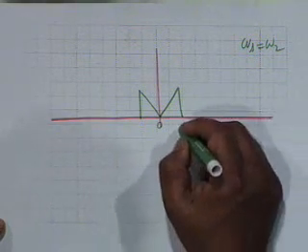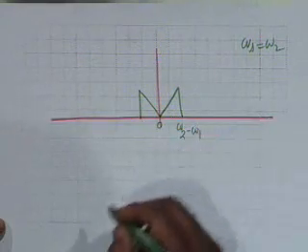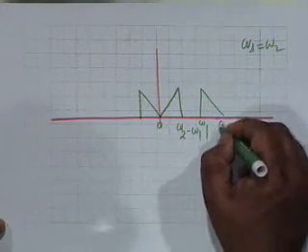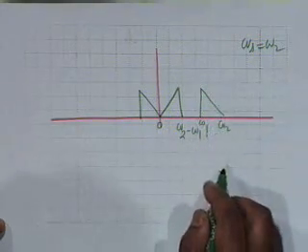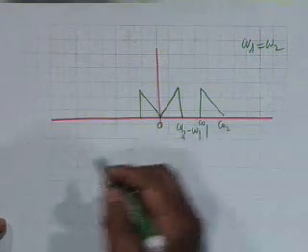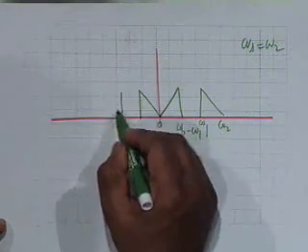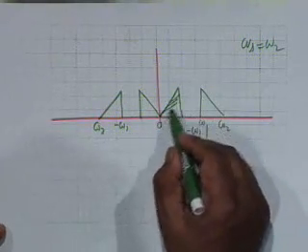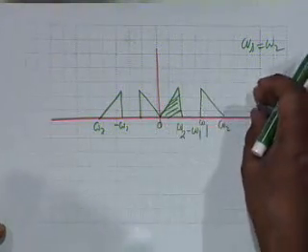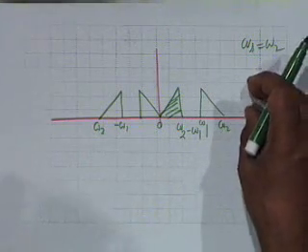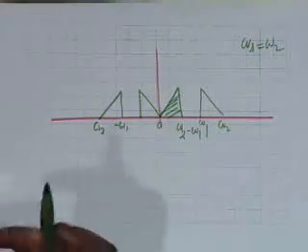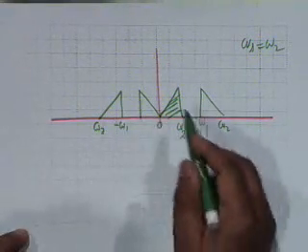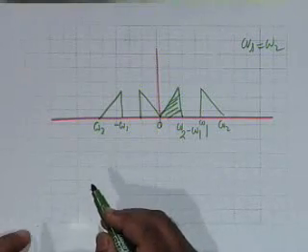Yes? Omega 2 minus omega 1, that is correct. Then we have omega 1 and omega 2, that is the original. Alright, then we have similarly on the other side, minus omega 1, omega 2. You recall that this triangle is the result of shifting this triangle to the left by appropriate choice of omega s. Now this picture is not quite what our original spectrum is.